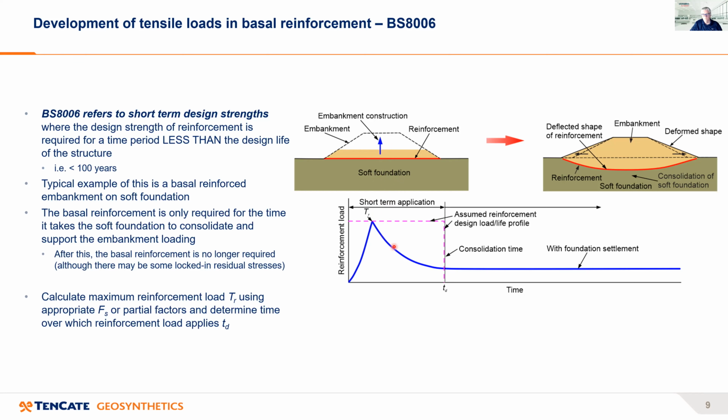It comes to a point out here where the soft foundation becomes fully consolidated, and at this point the soft foundation can support the full loading of the embankment by itself. So it really doesn't need the reinforcement anymore. After this, the load in the reinforcement remains constant with time.